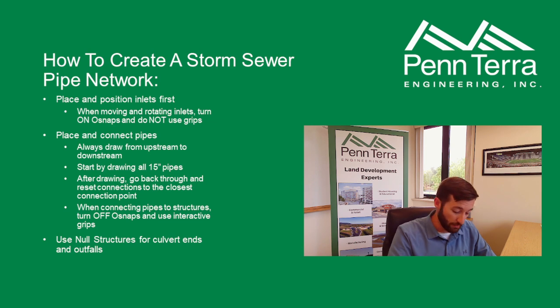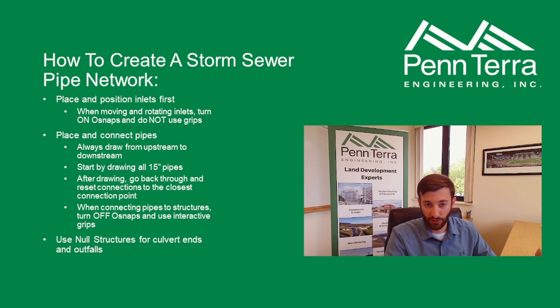Now, how to actually make your network. The first thing you want to do, and we're going to walk through it, but just kind of an overview so you know where we're going. I always start with making the inlets, and I don't connect any pipes to start out. So I insert my inlets using the dummy objects that I mentioned before, and then I move and rotate them.